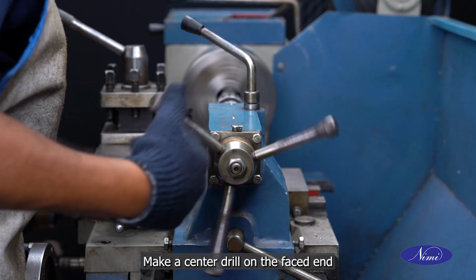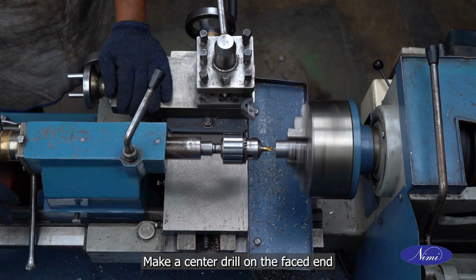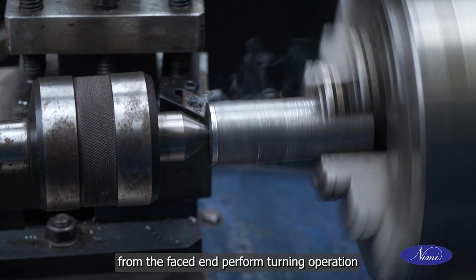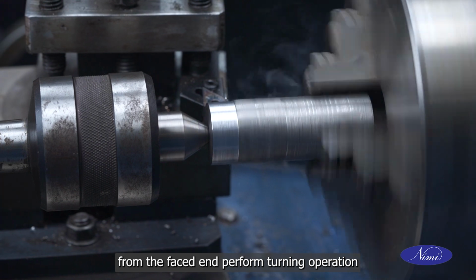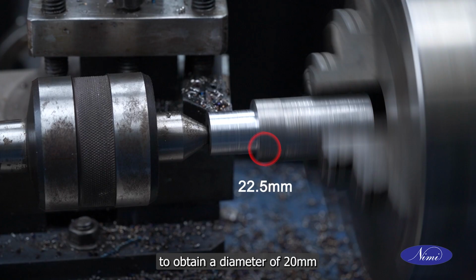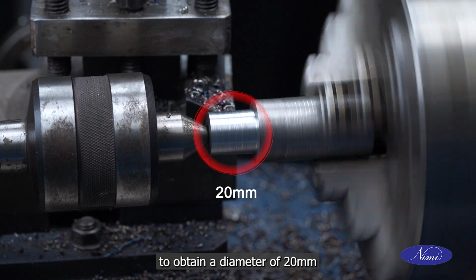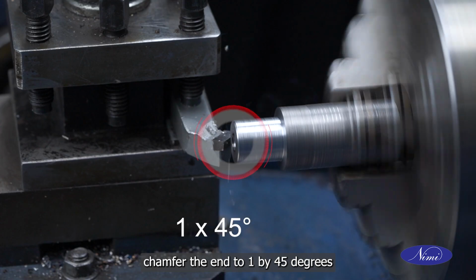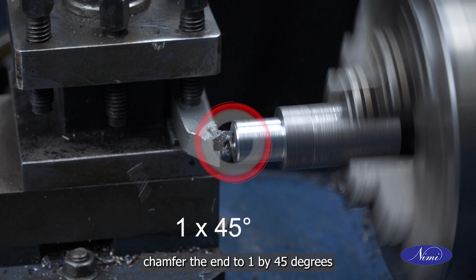Make a center drill on the faced end. From the faced end, perform turning operation to a length of 22.5 mm to obtain a diameter of 20 mm. Chamfer the end to 1 by 45 degrees.